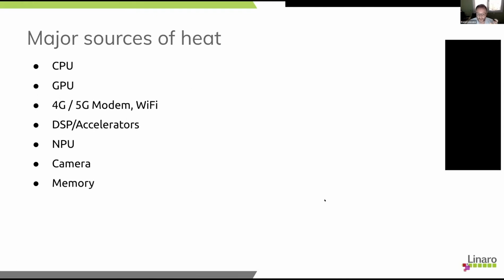Of course, during the last years the SoC has increased a lot in terms of density of components. With the components we have on the board, we have more and more components, the intensity of these components is increasing, and of course the sources of heat are also increasing. We can now find NPUs, we can find a lot of CPUs going faster and faster, and the memory is also going very fast. These are all sources of heat. And of course, we cannot have all of them working at full performance state at the same time.